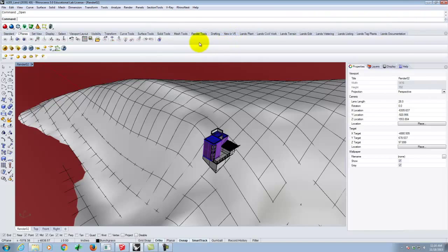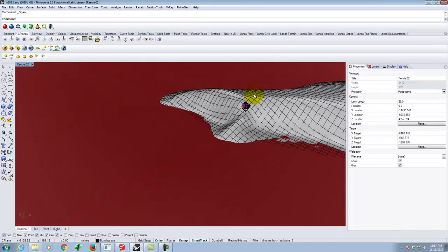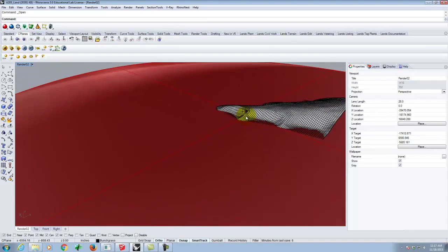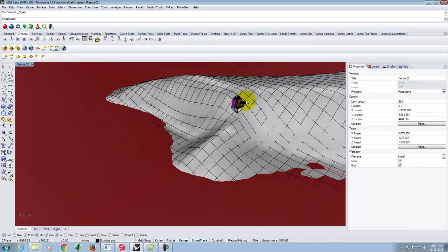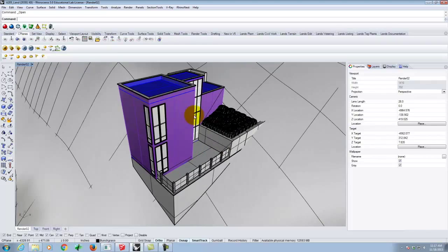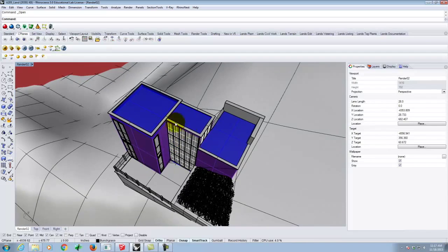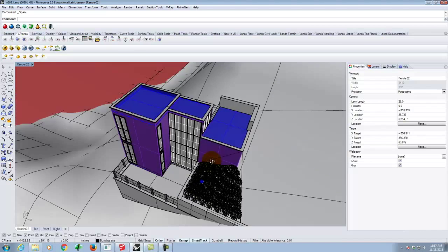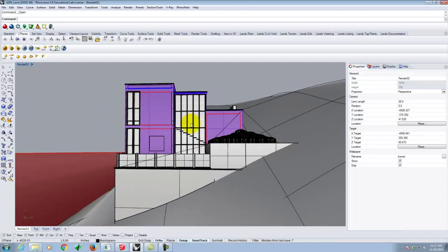There is also a toolbar which doesn't look like it's installed that sometimes will float in here as one of these little ribbons. For most of what we need, we can go straight from the Section Tools menu, or we can use the key commands. So what I'm going to start with is a plane that identifies what I want to section. In this example, I'm going to try to slice through the staircase in the middle of this model right there, and I'll try to have it looking in this general direction.